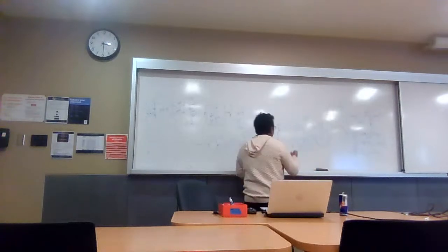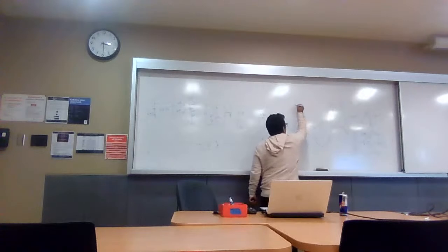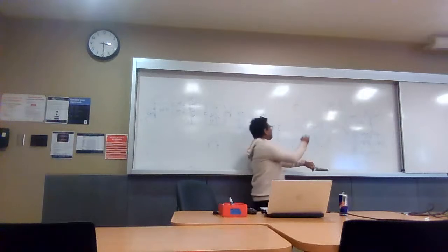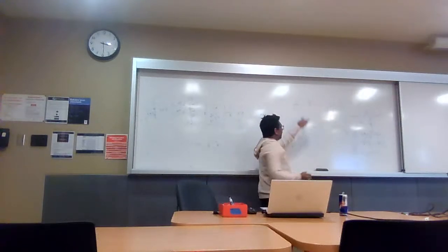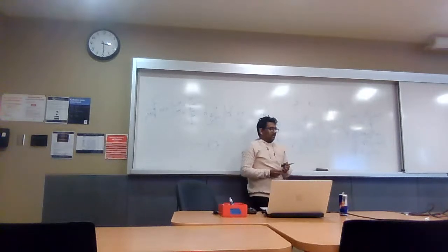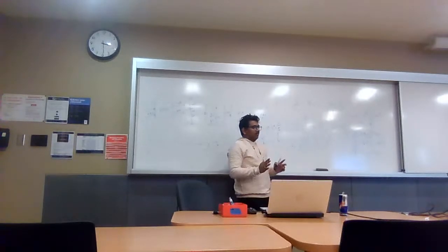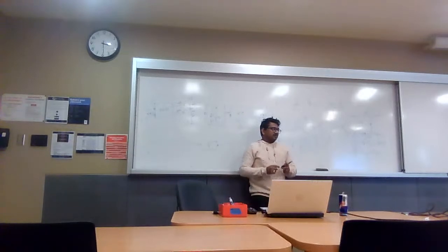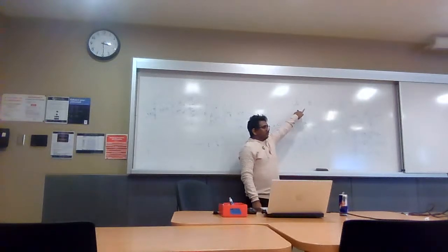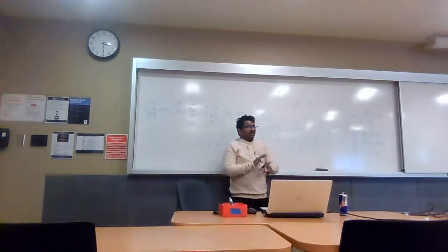Level means, if it is a clock, the flip-flops work on the edge, either the positive edge or the negative edge. But the latch works on the level, high level or low level, depending on the design. And therefore, flip-flops are used in sequential circuits. Sequential circuit means where we need a clock. However, latches are used in combinational circuits, where there is no clock. This is the basic difference. Any more questions?